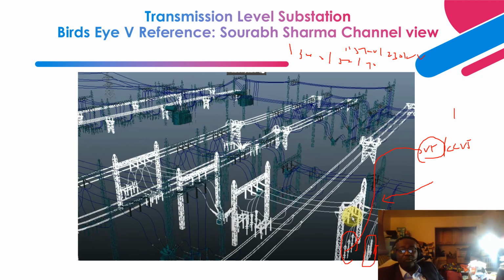But at voltages greater than 115 kV, it is more cost beneficial and economical to utilize a capacitive coupled voltage transformer. The difference between the inductive type of voltage transformer and the capacitive coupled voltage transformer is that the inductive one utilizes an inductive element, a wound transformer, and the enclosure has oil in it.